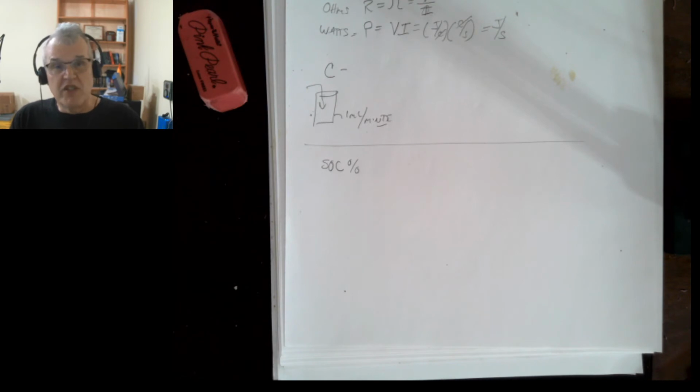For impedance, which is usually the way the manufacturers list their batteries, impedance is very simple, and I'll show you in a second. When we get done with this discussion, I'm going to show you how to do these different things that you need to do to check your batteries before you build a do-it-yourself Powerwall. So measuring the internal impedance is very, very important. And again, it's used rather than resistance simply because it's so much easier to do.